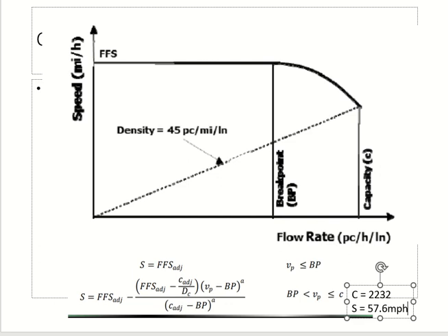Okay. Now one thing here, you can see you use this free flow speed, right? What we have, and you use the capacity what we calculated. But here they are saying use adjusted values. Why didn't we use the adjusted values?